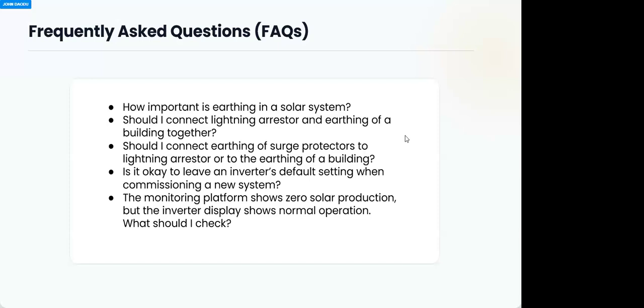You provide the system with the standard gauge of cable that can withstand the current, and the breaker. That's why it's important to rate all your component protective devices around the system properly, because if not, it will become a nuisance. For instance, if you put a low-rated battery breaker, and the battery demands 200 amps, and you are putting a 100 amps breaker.